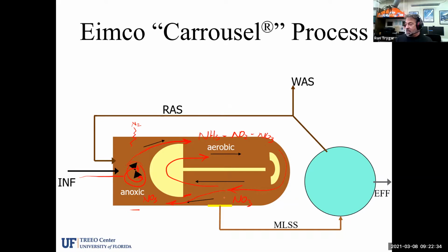It uses the same idea. The outlet gate right here is where the mixed liquor flows over the gate out of the oxidation ditch into the clarifier, and we hopefully have gotten most all of the nitrate out, but you may still have just a little bit left going out of the facility. So it's not as much as the influent ammonia that was coming in, around 30 or 40 milligrams. So we've done a pretty good job. Is it 100% effective at reducing it down to 0? No, it probably is not, but it will do a good job.